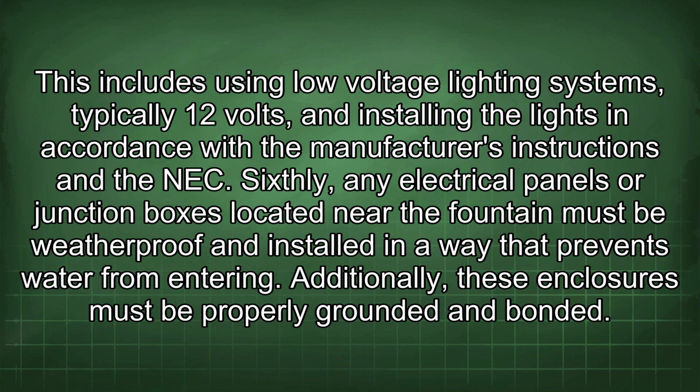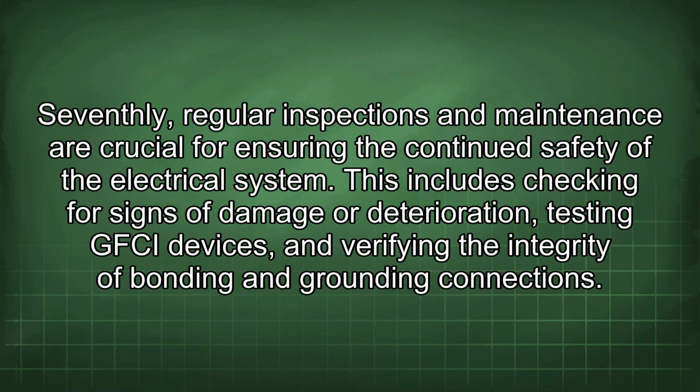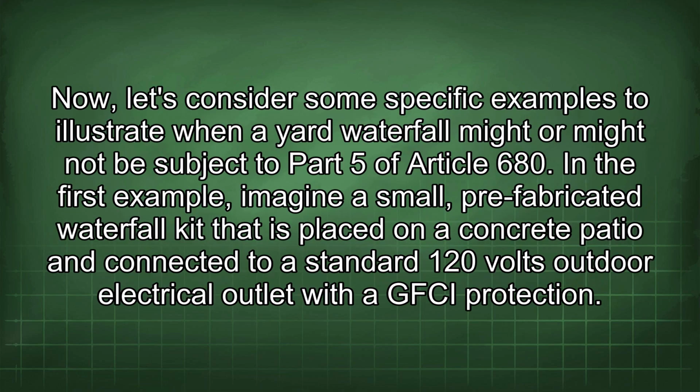Additionally, these enclosures must be properly grounded and bonded. Seventhly, regular inspections and maintenance are crucial for ensuring the continued safety of the electrical system. This includes checking for signs of damage or deterioration, testing GFCI devices, and verifying the integrity of bonding and grounding connections.